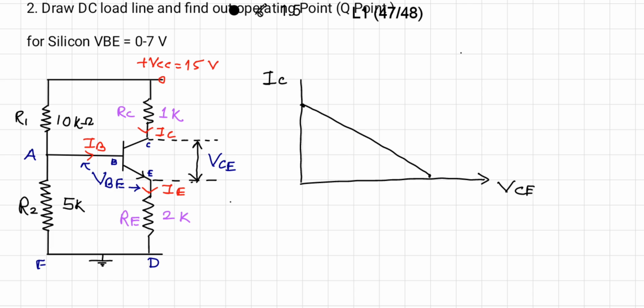There it is a line, this is called as a DC load line, and here we get somewhere a Q point, that is zero signal collector current and collector emitter voltage. So we have to find out this, that is first thing. So we have to draw this DC load line. So we must know the voltage VCE when IC is 0, and when VCE is 0, what is the maximum current that we want to find out in this circuit.